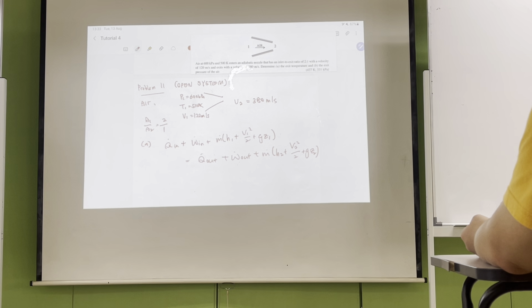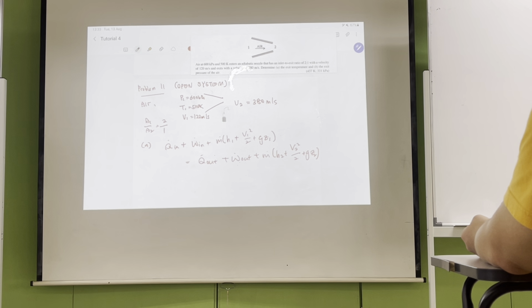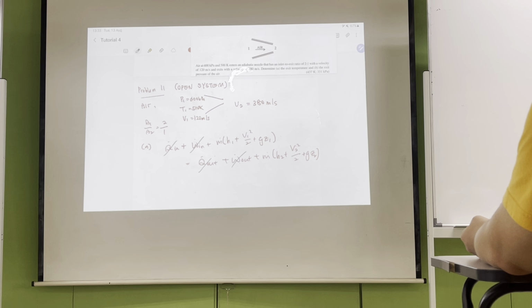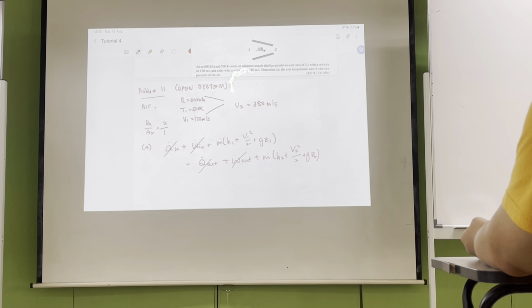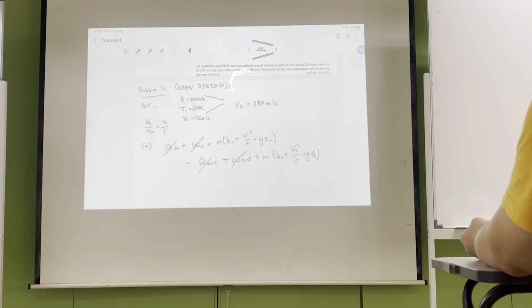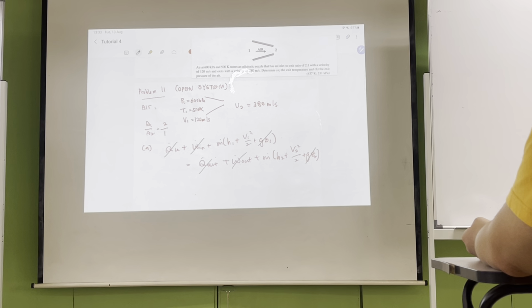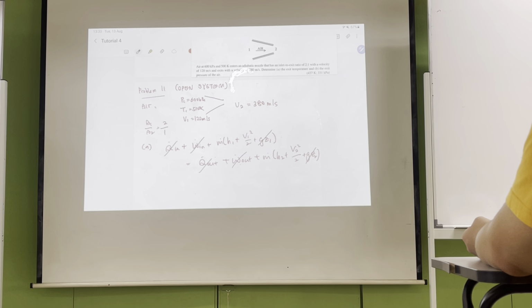Okay, so for a nozzle, we don't really have any change in work. Since we are told that this is an adiabatic nozzle, this one you can solve as well. Of course, if the question says there is energy loss or gain, then you follow heat loss or heat gain. But otherwise, just cancel them off since it says adiabatic. Potential energy, 99% of the time we cancel this off. Mostly you won't get any example that requires this. But again, it's question dependent, so you read the question.